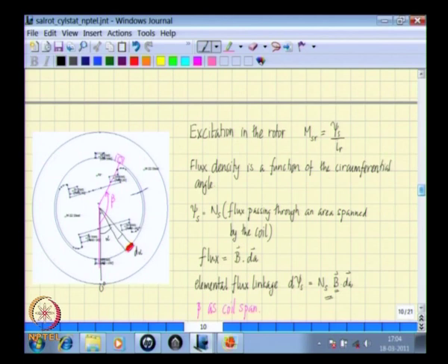In this geometry, what is happening is that the flux lines would travel along the rotor and then go into the stator and then come around and complete the flux loop in this manner. We have also noticed that in the air gap areas there is bound to be very little flux. Majority of the flux is going to go through the pole faces.